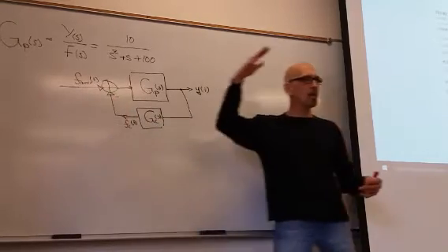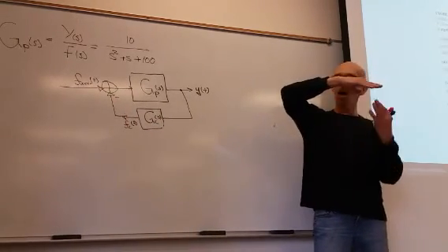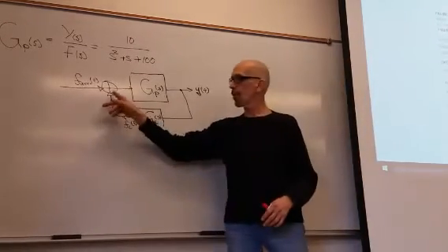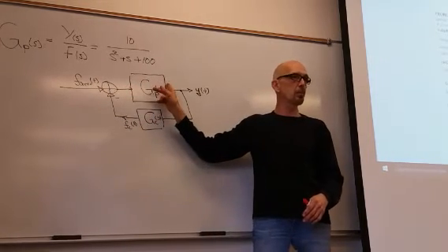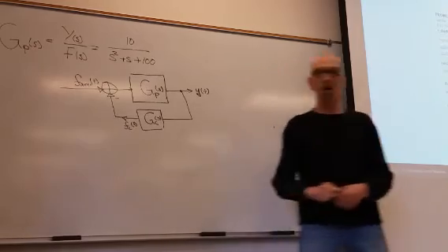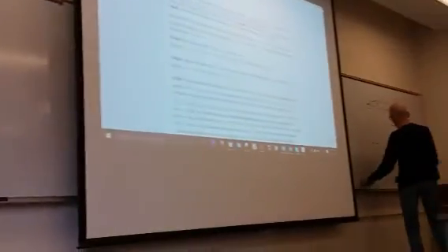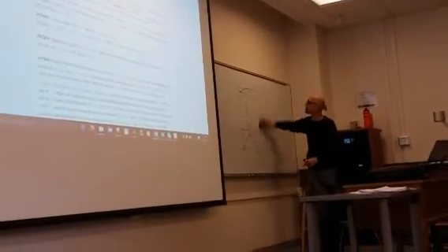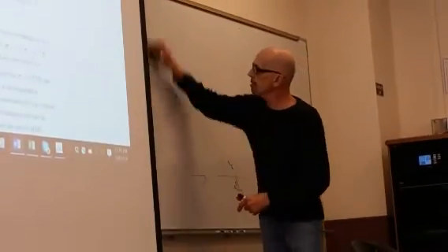But anyway, it's the same thing here. If the aerodynamic forces are pushing down on a tip at a given point in time, you want that actuator to push it back up. So you subtract a force from a force. And it's that force difference that excites the tip of the wing, which is your second order model. So let's first of all say that we want a type M closed loop system. What kind of system is this block diagram? Is it a command system?